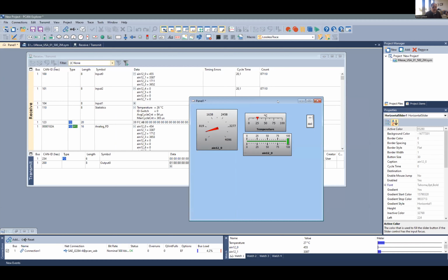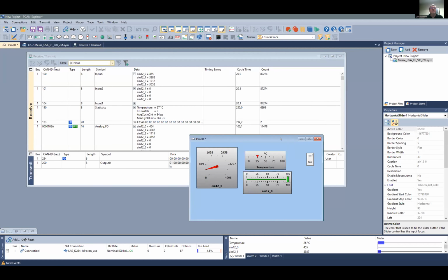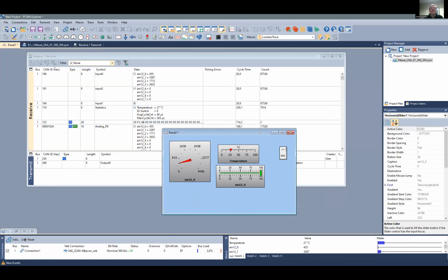Also, it's a raw CAN analyzer. The problem is if we start to implement such tools inside the PCAN Explorer, it gets more difficult to train and it's too complex then. It is a CAN analyzer for layer 2 with symbol based and J1939, but flashing ECU, things like that, is not supported by the product.